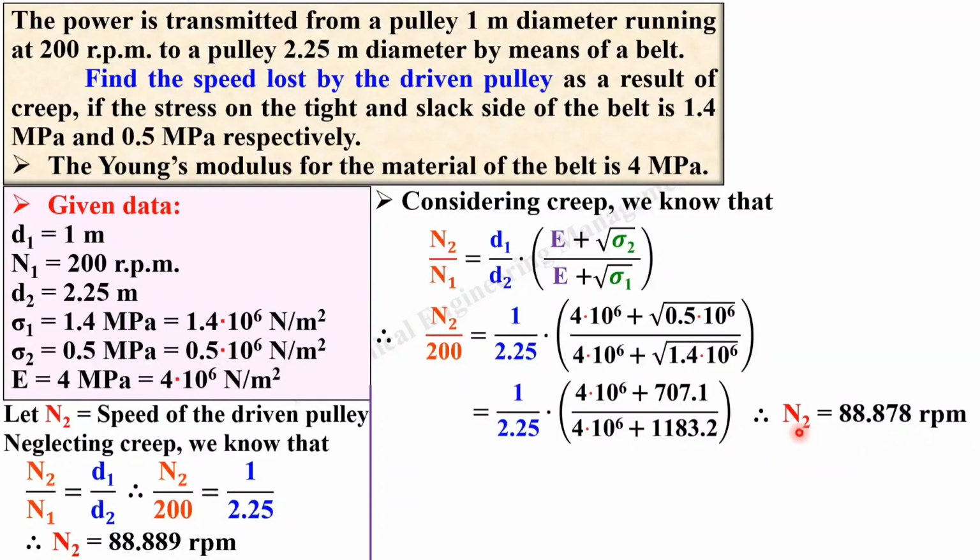Here this N2 is the speed of the driven pulley by considering the creep. Here this N2 is the speed of the driven pulley without considering the creep. Our objective is to find the speed lost by the driven pulley as a result of creep. This is the speed without creep, and this is the speed considering the creep. So this is the speed loss, because this value is greater than this one. Why is this value less? Because of the creep.